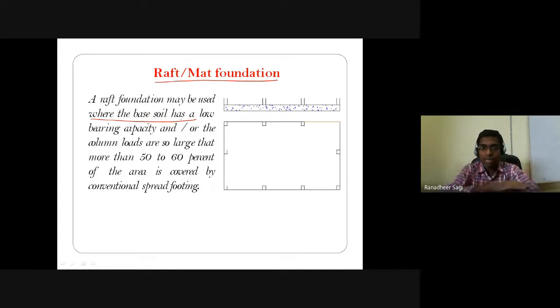So a load over a large area is going to give you a lesser pressure distribution from that foundation onto the soil. So though the bearing capacity of the soil is less, as the pressure you are trying to transfer through that raft onto the soil is less, it can meet the criteria of the bearing capacity of that soil without causing any failure in your foundation, by preferring to go for what is called a raft foundation.